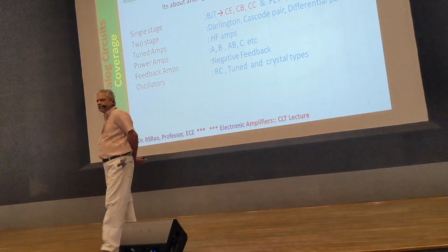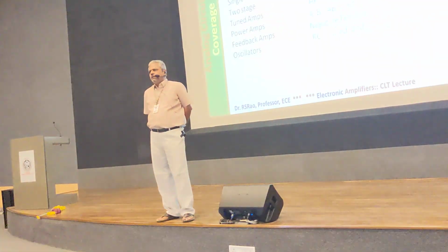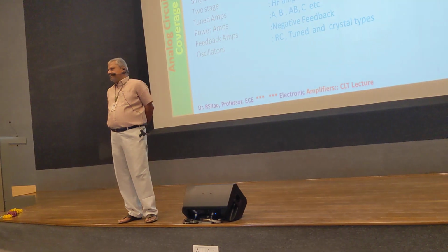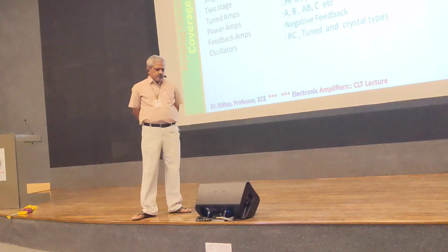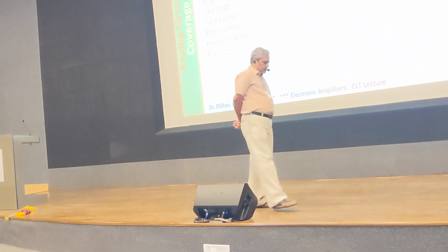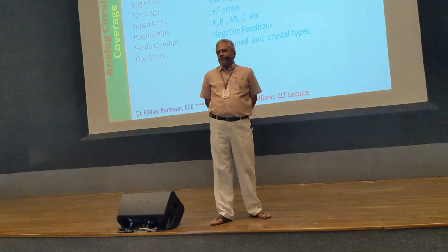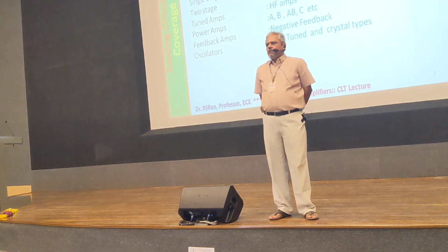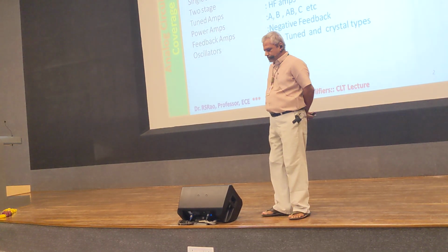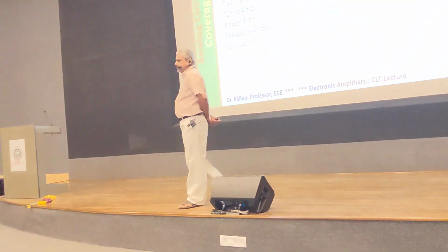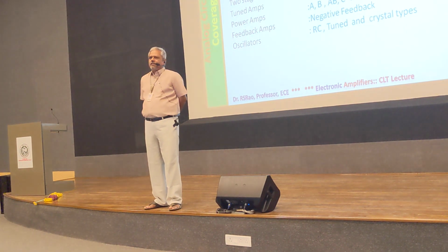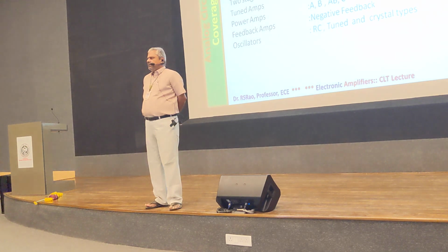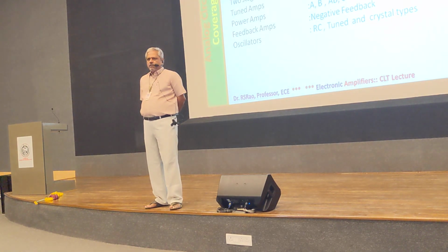In the same way, when the output impedance of the amplifier is small, this amplifier starts loading the next stage of the amplifier. So impedances of circuits and devices, in particular amplifiers, are quite important specifications. Of course, you all know an amplifier is there to provide amplification. What is amplification? Amplification means making a small signal into a large signal.